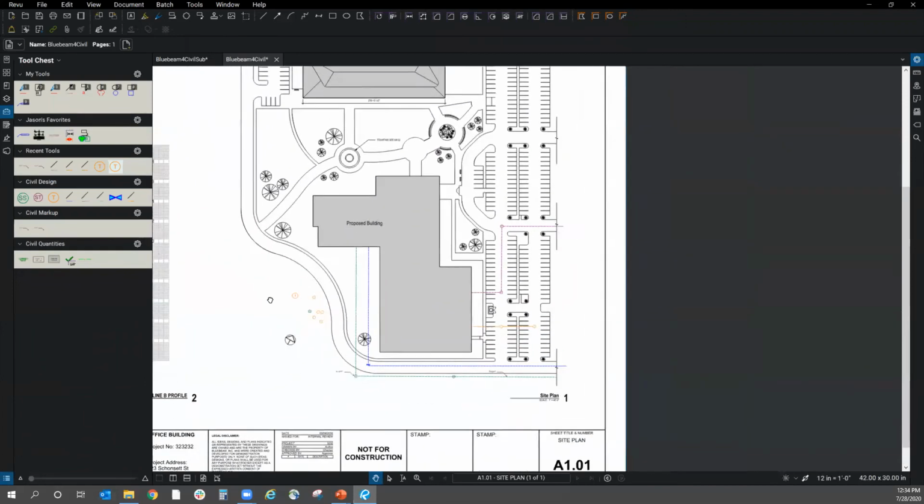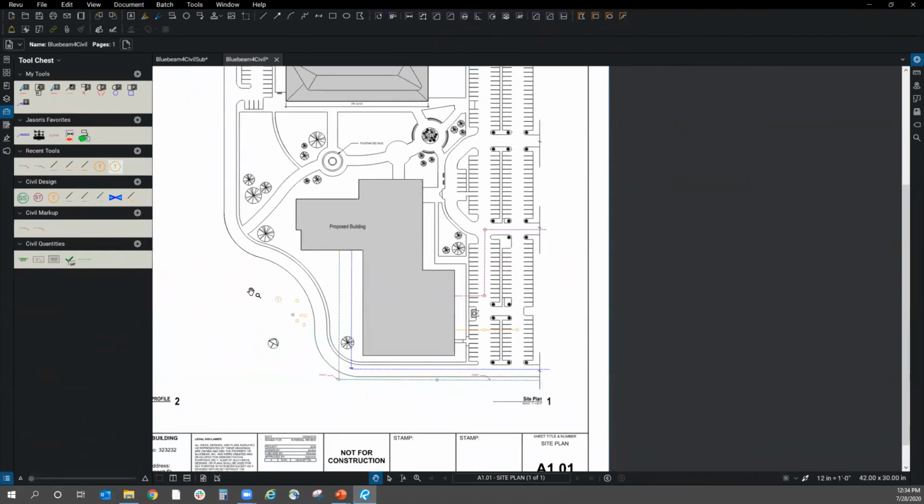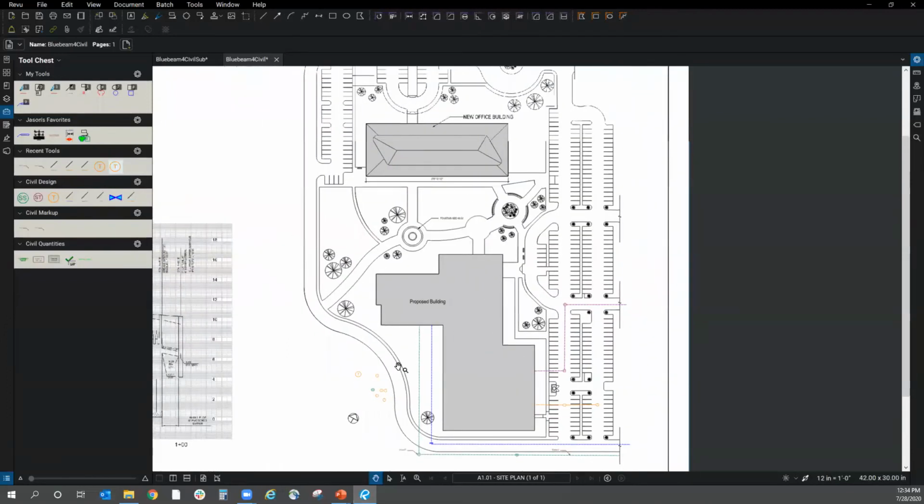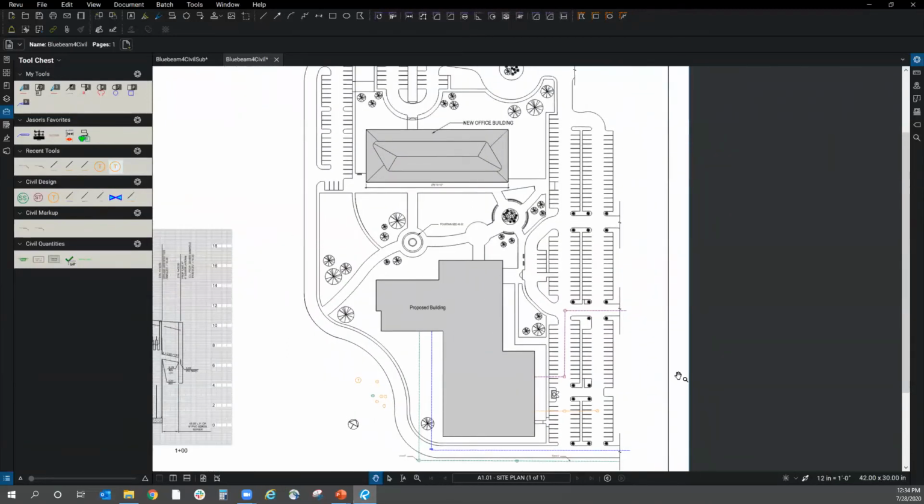And, you know, so we've used Bluebeam Revu to do some preliminary layout. We've made a couple markups that are already in here. Well, let's start talking about our quantities. How can I configure these as well? And if I hover over this, you can see I've got a landscape one, an asphalt, a concrete, a count, and a length. So as with everything in Revu, anything that we create can be reused.